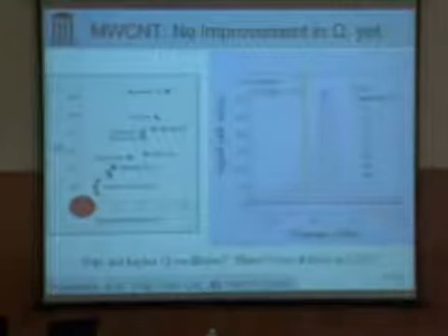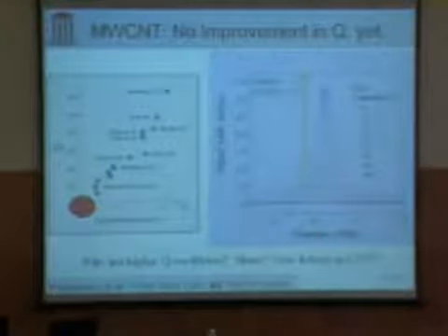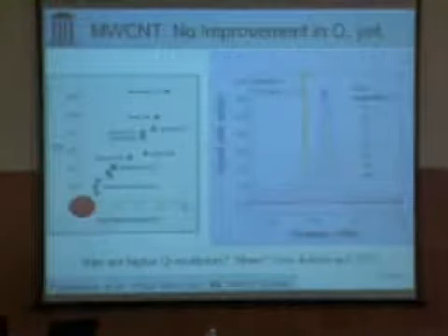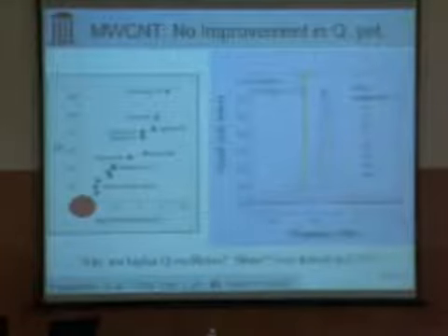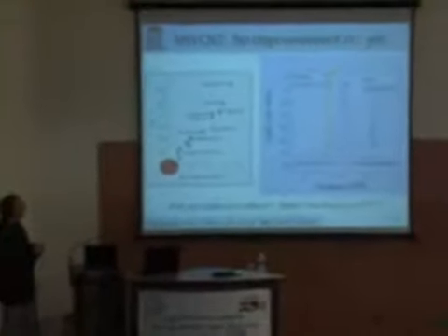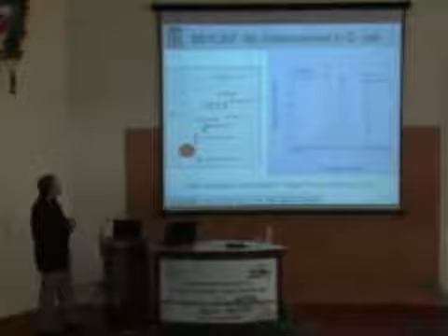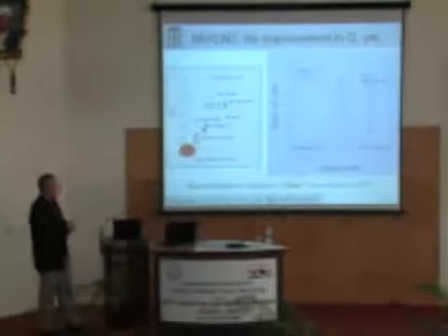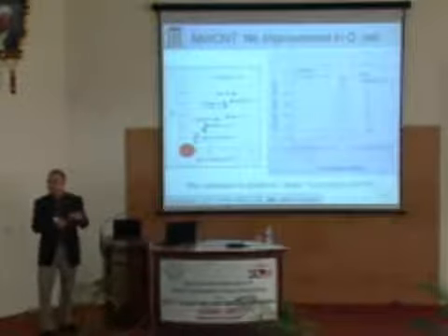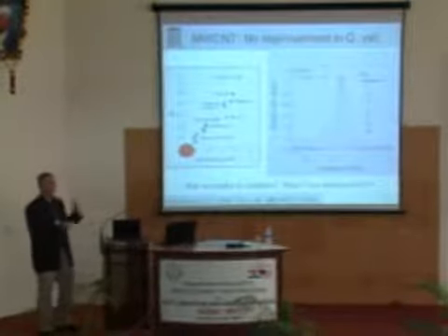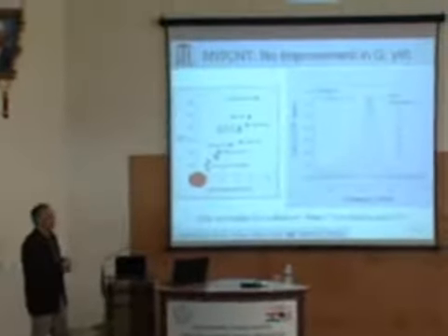One of the goals with devices is to get high Q, which means low energy loss, which means high sensitivity. There's a problem, though, in the electromechanical field. What I'm plotting here is Q versus the size of the device. And this isn't talked about very often in the nano device area. But this is a set of devices over the years from 78 to 2000, and how the Q has gotten worse as the device gets smaller. And that's because the nature of the energy loss in these systems doesn't scale favorably with the change in the resonance frequency as you go down.